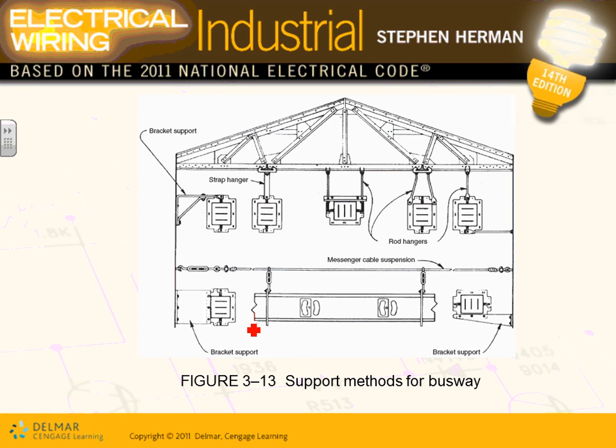Here's how it looks, guys. You can support the busway through a messenger. I don't know if you guys can see that. Then you support my busway from here. That's what they call messenger. Bracket support. Here's my bracket support. You can also support it this way with bracket support. You can use strap hangers. Look at that one, strap hangers. Bracket support that looks like this. What else? Rod hangers. You have your rod hangers hanging them.